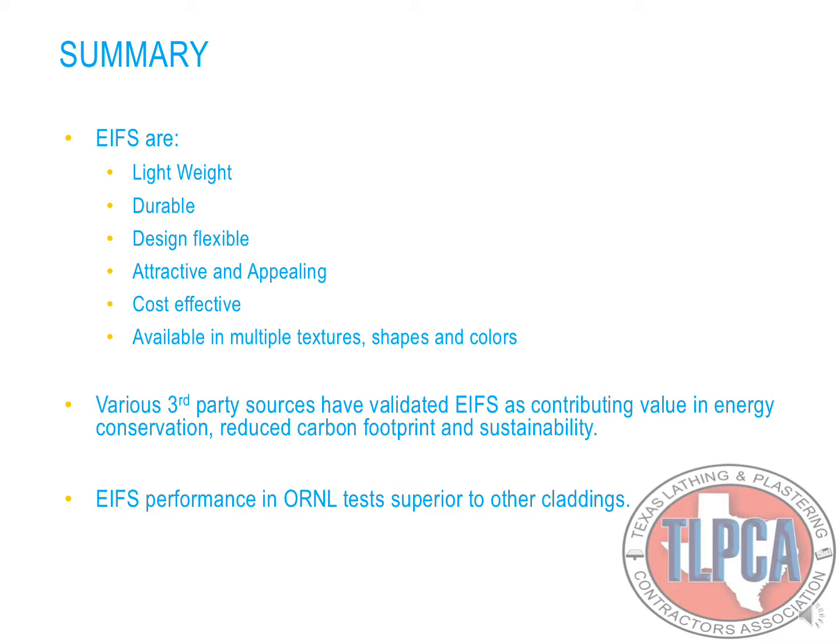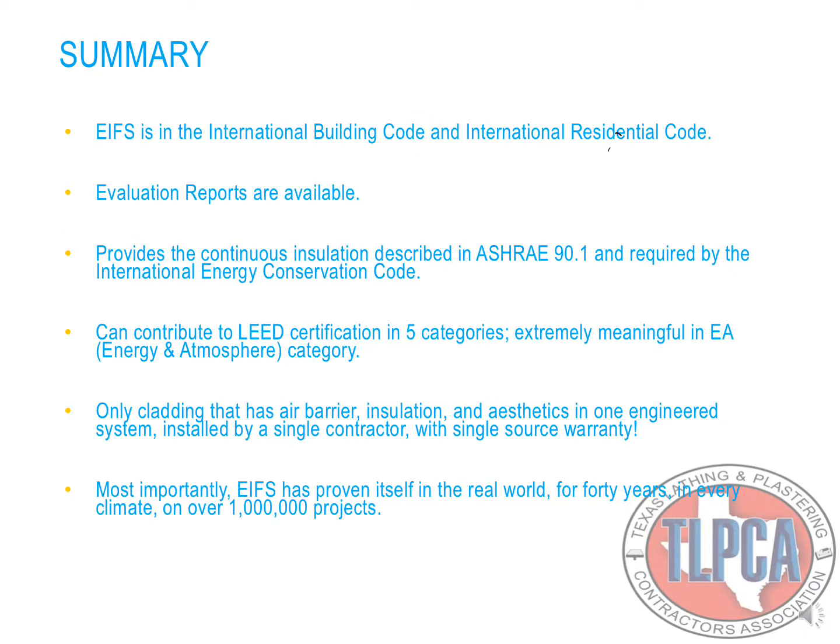EIFS performance in ORNL tests are far superior to other cladding. EIFS is in the International Building Code and International Residential Code. Evaluation reports are available. EIFS provides the continuous insulation described in ASHRAE 90.1 and required by the International Energy Conservation Code.